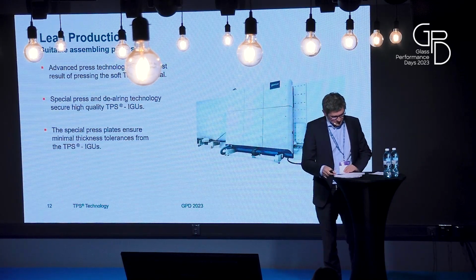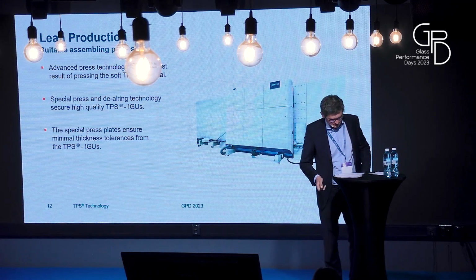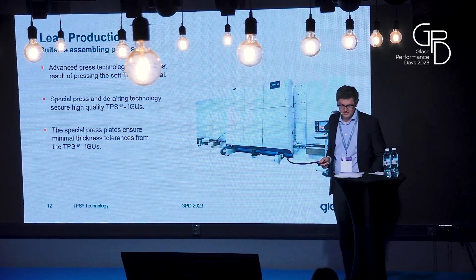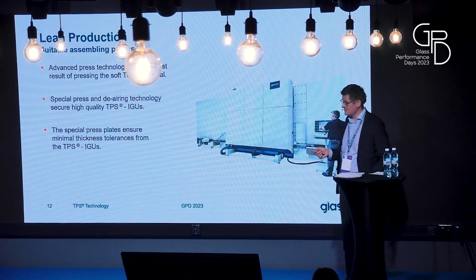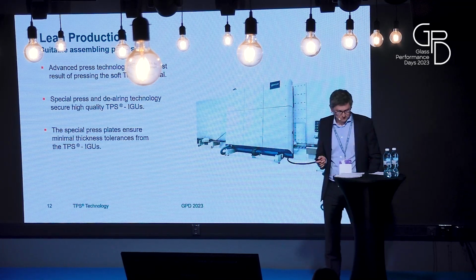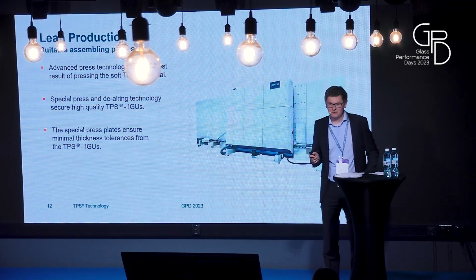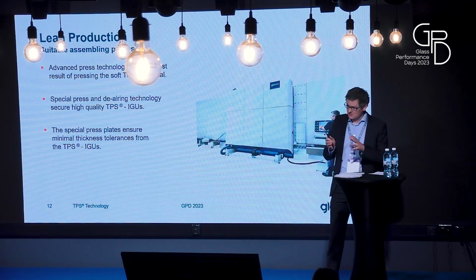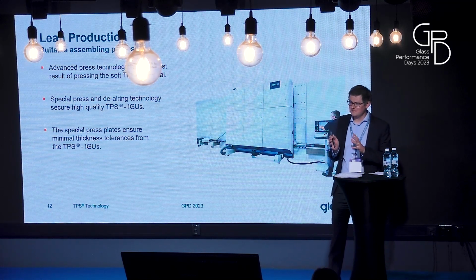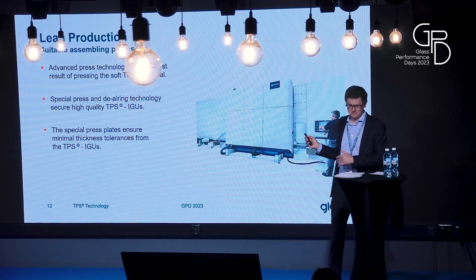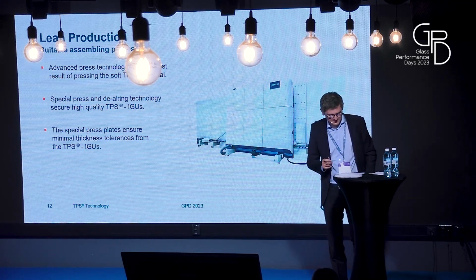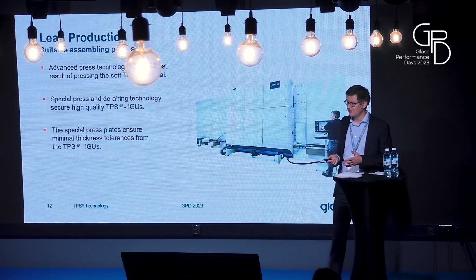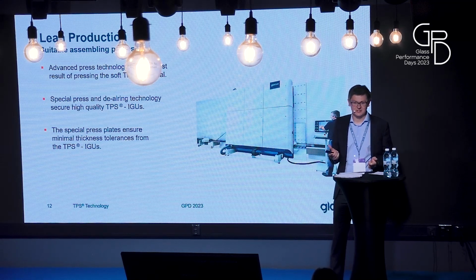And besides the application itself, there is another very important process, and this is the pressing of the IG units. You should know that assembling, pressing, and gas filling of rigid spacers is completely different compared to TPS. And the main reason for that is the properties of the material. On one side, softness, and on the other side, gas tightness.